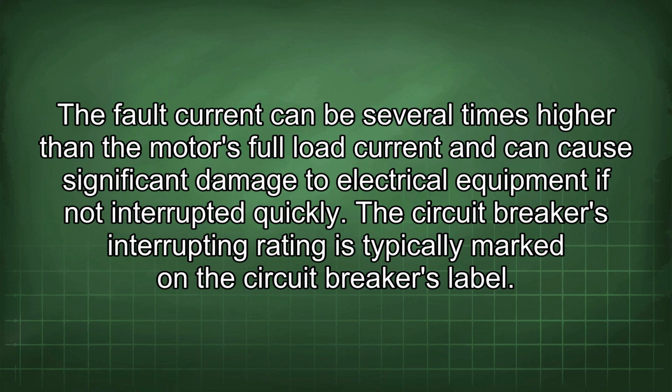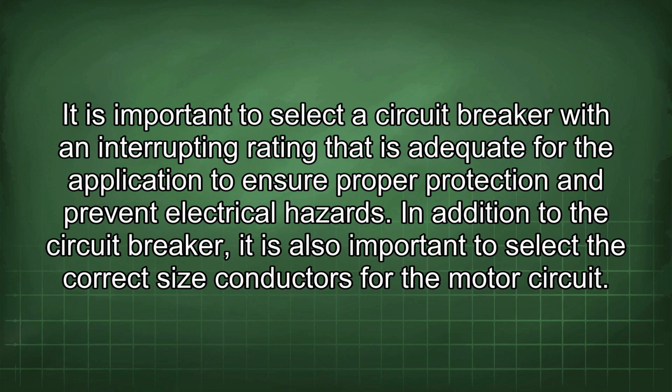The circuit breaker's interrupting rating is typically marked on the circuit breaker's label. It is important to select a circuit breaker with an interrupting rating that is adequate for the application to ensure proper protection and prevent electrical hazards.